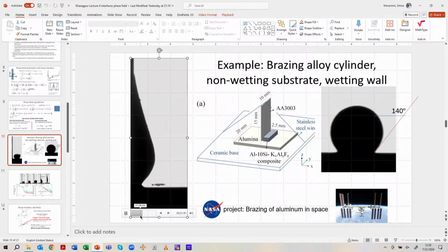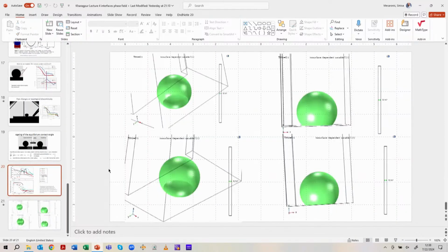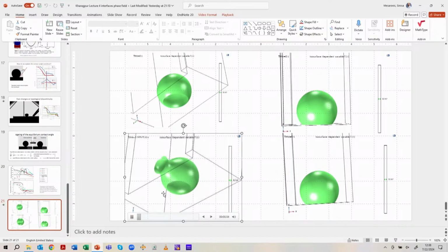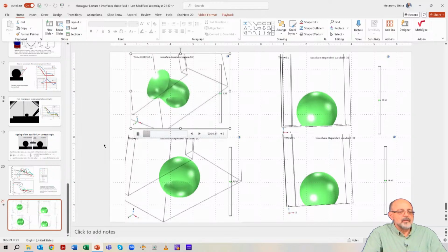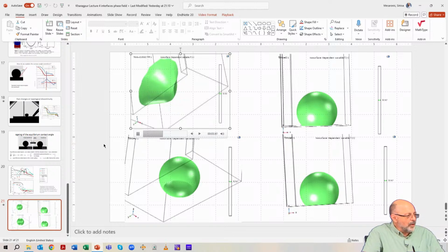So the effective viscosity is high, and in that case, you will get this separation. In the case of low viscosity, if it gets the time to melt all the crystallites inside, and then it touches, then you have a low viscosity fluid, and this will happen. So you will have a gradual transition.